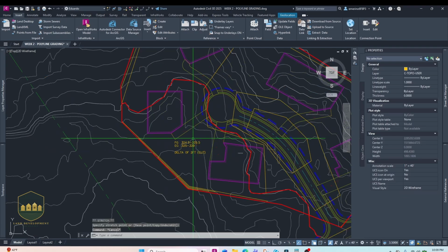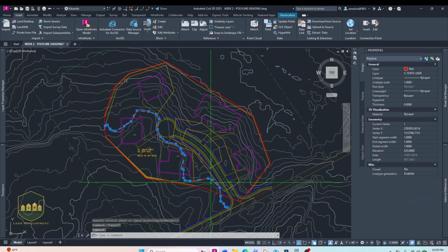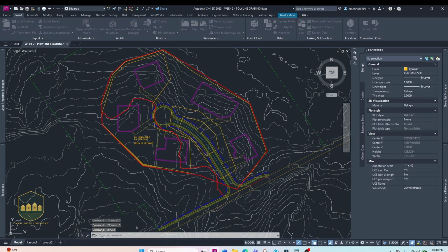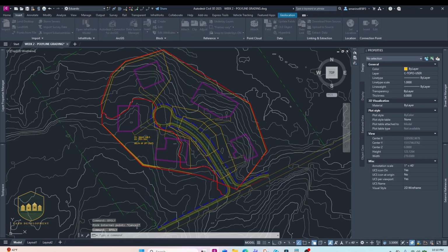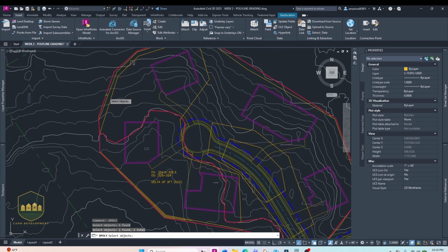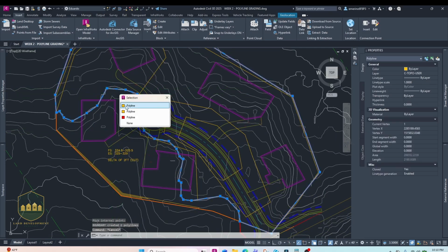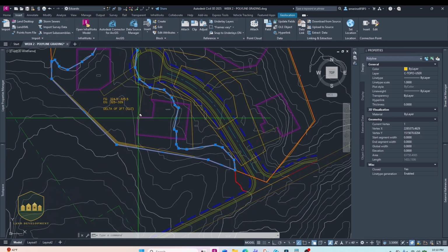Very nice. And then the next thing I want to do is, let's see how nice I am. I just want to get the square footage of this area so I can see how bad we are. When I do B poly, this comes up. I just select the lines, this line, and yes. Dang, I am nice. What it's doing is just making a nice closed polyline of what's already pretty closed up.